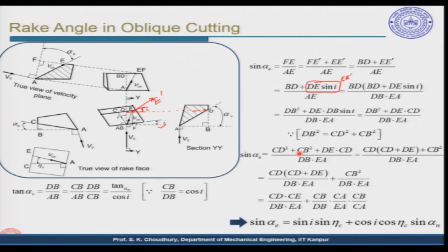Now, the velocity rake angle is measured in a plane parallel to the cutting velocity vector and normal to the work surface.